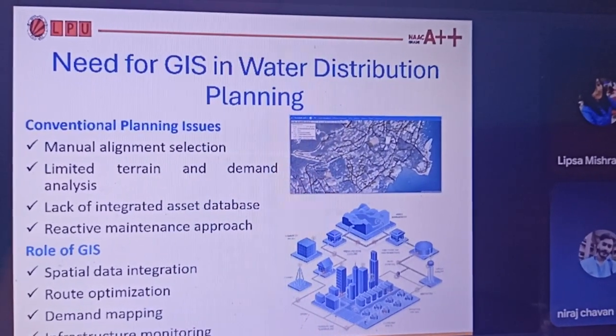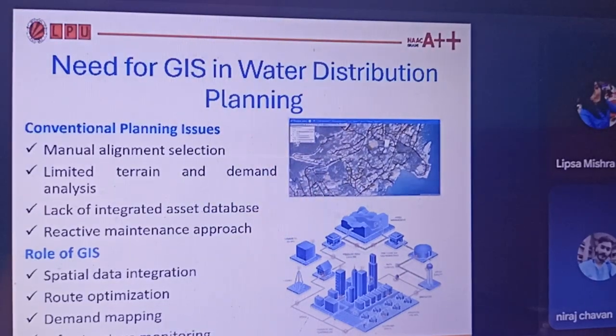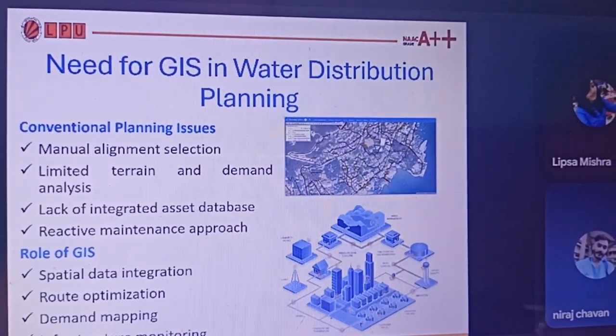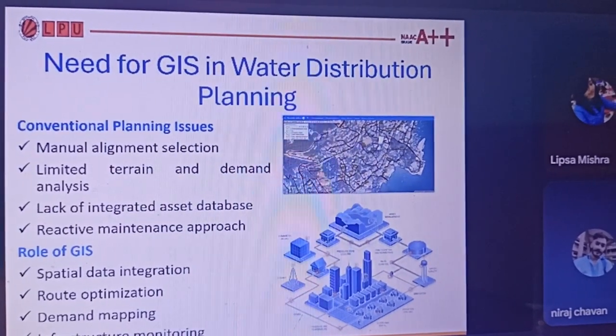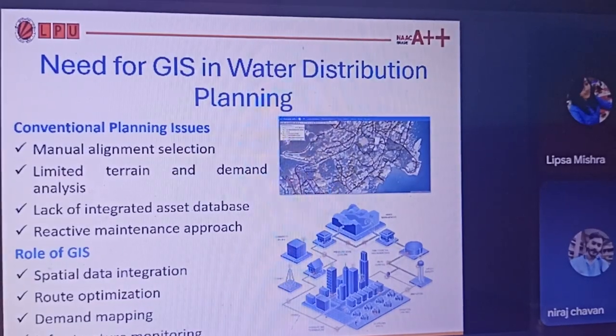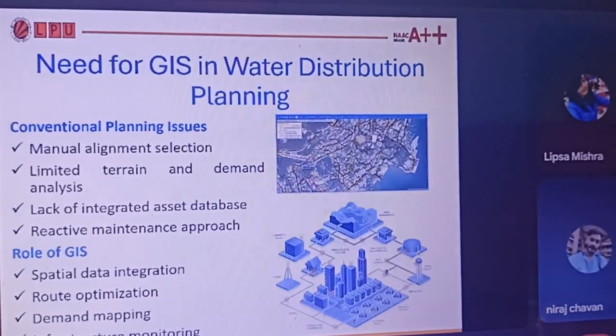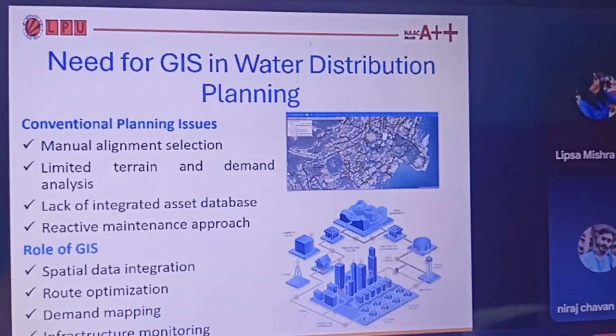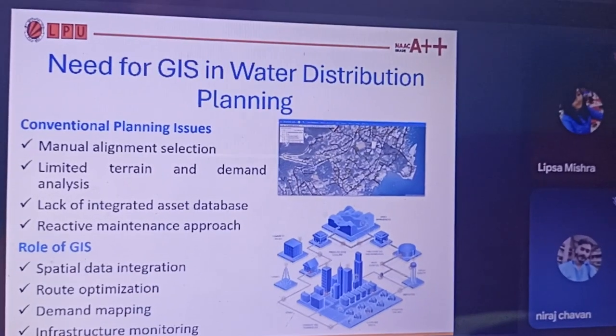Okay, so in urban areas, we'll be supplying 135 liters per capita per day. So if in my house we are a family of three, then 3 multiplied by 135 liters of water will be coming to my home anyway.